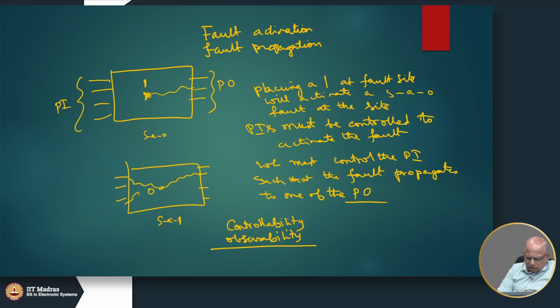As I told you earlier, that is the satisfiability problem. Can I set this wire to a known value like 0 or 1 by only controlling the primary inputs? So, that is a tough problem. It is solved by backtracking, right, and in the worst case we may end up trying all kinds of inputs at the primary inputs. In the worst case, all the 2 to the power n, if there are n primary inputs, I may end up applying all the 2 to the power n inputs.